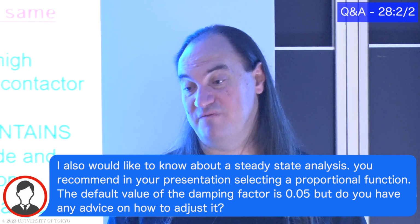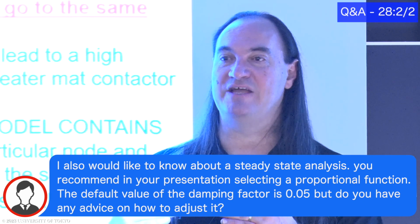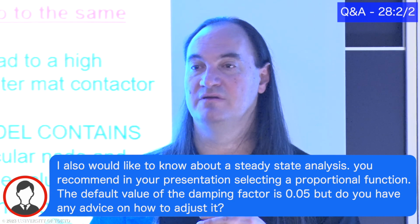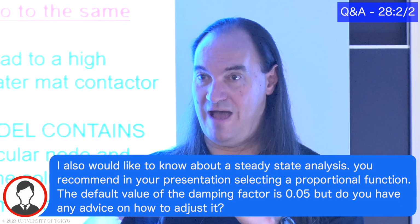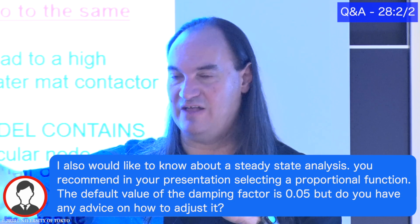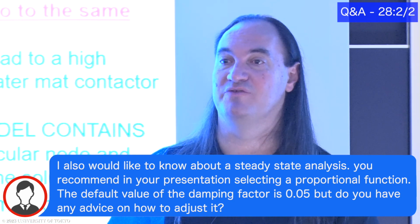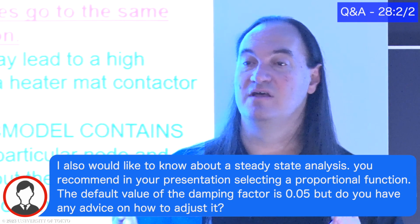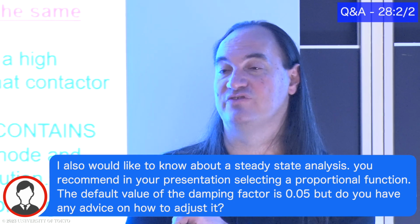And something to do, if you do that, is write your own logic such that at every iteration, you output the power and the temperature for the heater. So then you can really see, okay, what is it doing as it marches through iterations? Is it oscillating more? Is it oscillating less? So that you could get the data to be able to evaluate better, rather than just say, okay, well, tell me what the final number is. Get intermediate data to understand what the trending is as the solution is progressing.